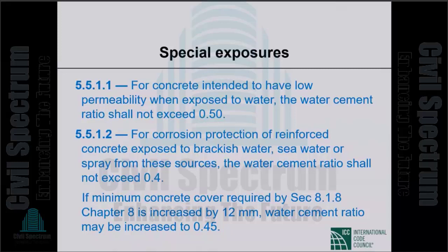Okay. So when we talk about durability, the various aspects of it, there are typically four. Freeze thaw resistance, which is kind of moot in Bangladesh. So you have three considerations. One is resistance to sulfate attack. Second is water tightness, permeability, however you want to describe it. And the third is corrosion protection.